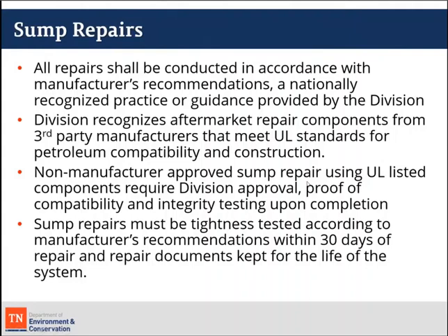The division recognizes aftermarket repair components from third-party manufacturers that meet UL standards for petroleum compatibility and construction. Non-manufacturer approved sump repair using UL listed components requires division approval.